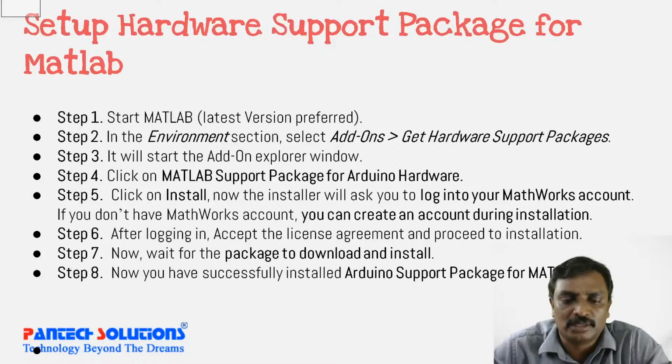There are 8 steps involved. First, start MATLAB, then go to the environment section, go to add-ons, and click hardware support package. It will start the Add-On Explorer window. There you have to search for the MATLAB support package for Arduino hardware. Then you log in, it will ask for a MathWorks account, which is a free account you could create. You accept the process, then it will automatically download and install the package. After that, the Arduino package will be installed, then you could open Arduino.